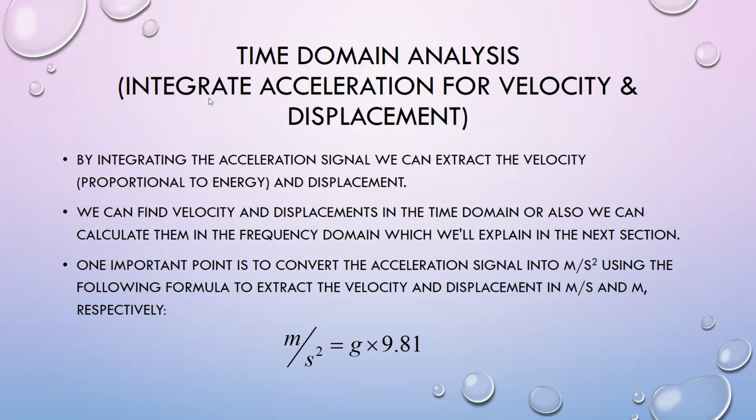Okay, as I told you, the last application of this data in the time domain is to calculate the velocity and displacement by integrating the acceleration. So we can find the velocity by integrating the acceleration, and also by integrating the velocity, we can find the displacement. Also, of course, we can use this method in the frequency domain to extract the velocity and displacement in frequency domain.